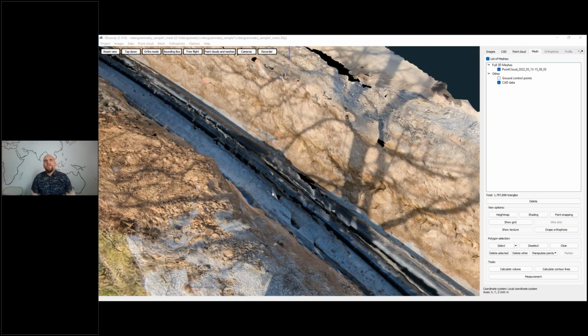So here for areas, I would say up to 50 meters apart, but I would recommend you to use, for example, 8 ground control points for your project. So probably most of your projects will be 200 meters or shorter or something like that. So in that case, I would just place 2 points on the edges. So 2 points on the start and 2 points on finish.